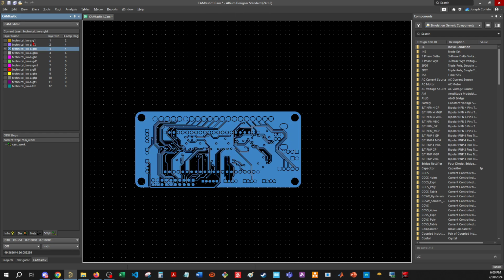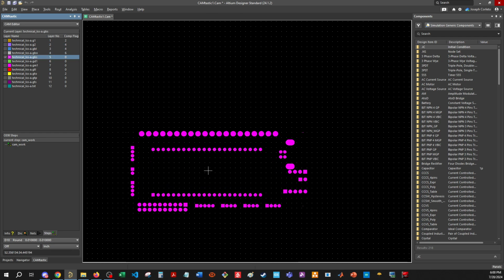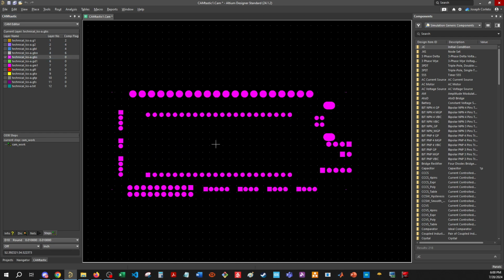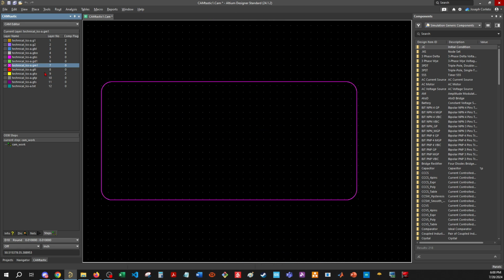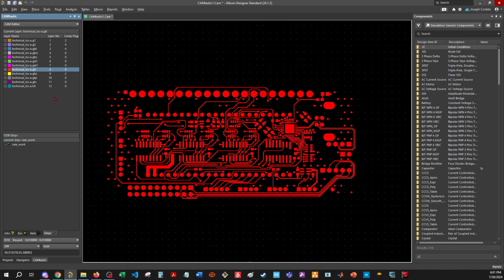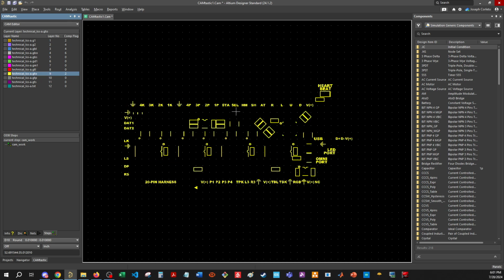It's for you to look through the files, see if any kind of errors show up. This is common when you go ahead in Altium and generate Gerbers. It'll automatically make a CAM document for you to inspect, which is great. Sometimes, let's say a few days pass by and you forgot what you did, or you want to check some detail, and you really don't want to go ahead and open up Altium Designer's PCB editor. Let's say you just want to open up this.